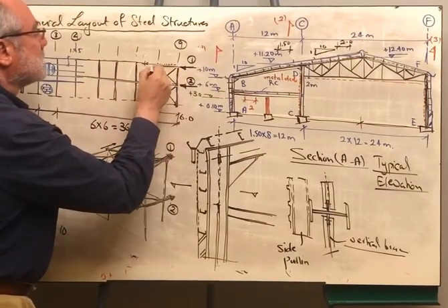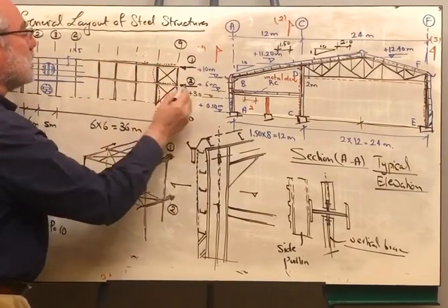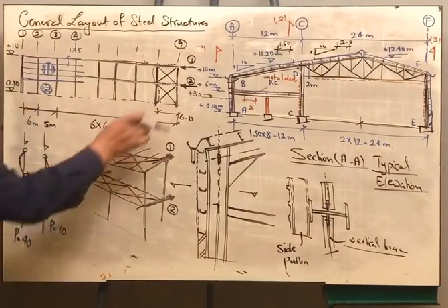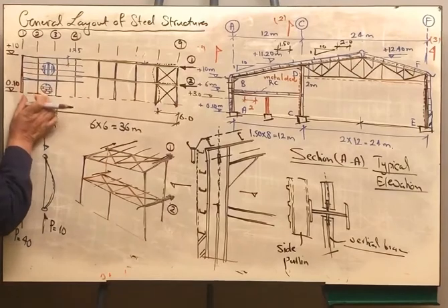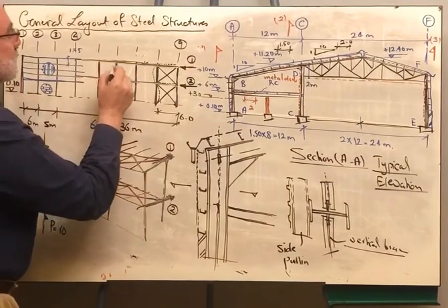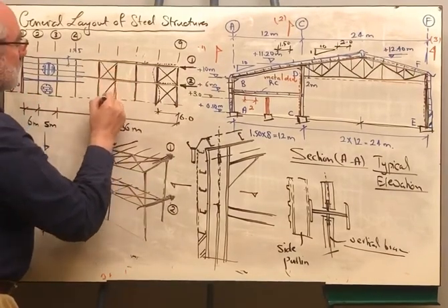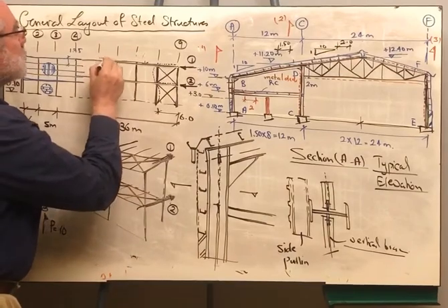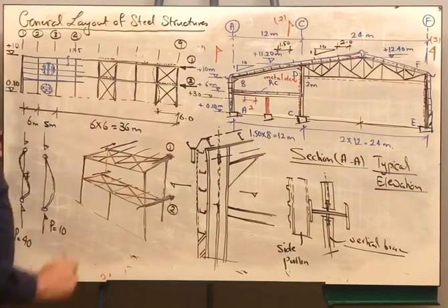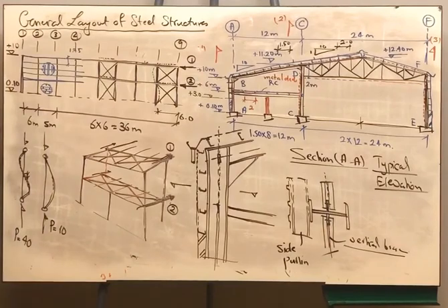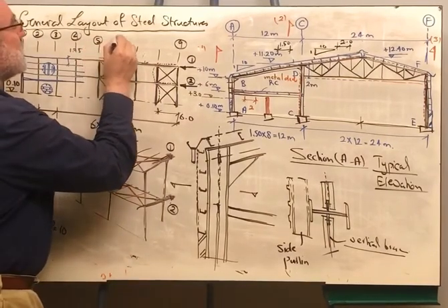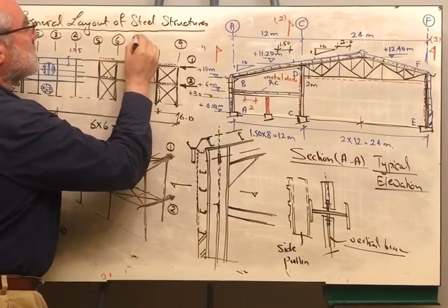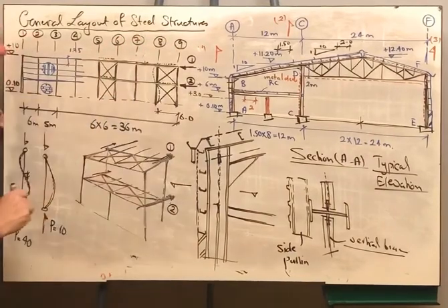Therefore, this strut or this bracing system should continue throughout the hall. And I will provide vertical bracing here, vertical bracing there, and vertical bracing in the middle. And I should indicate the presence of the upper bracing and the bracing at the level of the mezzanine. This is axis 6, 7, and 8. So this is a complete view.